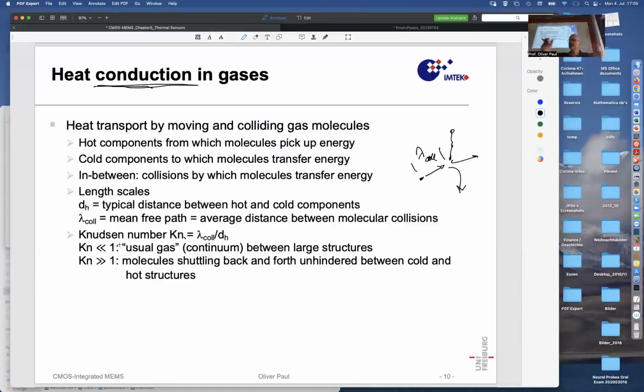And then the gas can be considered like a continuum, like a non-dense, very thinly populated solid. Sparse. Dicht, dense, and then flüchtig, volatile, maybe. So in this gas with many collisions, you can say it's like a solid that does not conduct very efficiently, but the heat transport equations are the same as if it were a solid. It's just a kappa that is low.